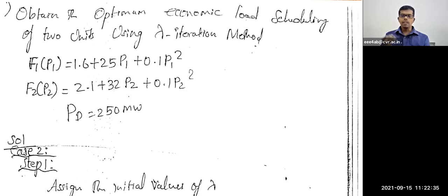Sometimes you write the problem correctly in the notebook, but while substituting, you wrongly substitute some values, and further proceeding with the same problem will give the wrong value. Even if you solve for half an hour or 1 hour, or even 5 iterations, it will come out wrong. So you have to do this carefully. Once you note down the fuel cost coefficients clearly, then you proceed and can easily solve this.